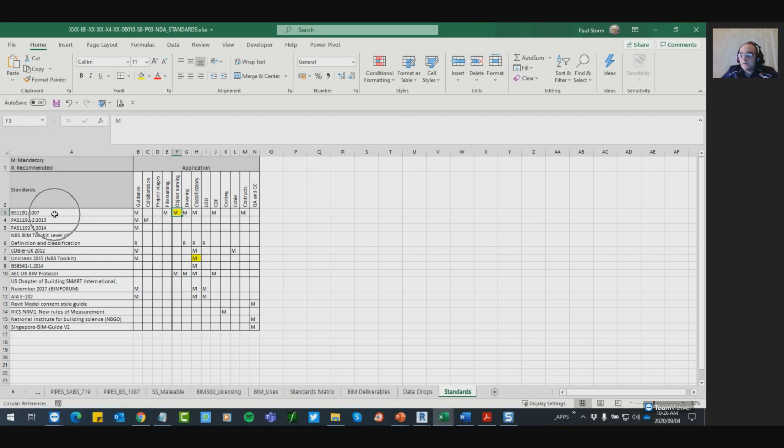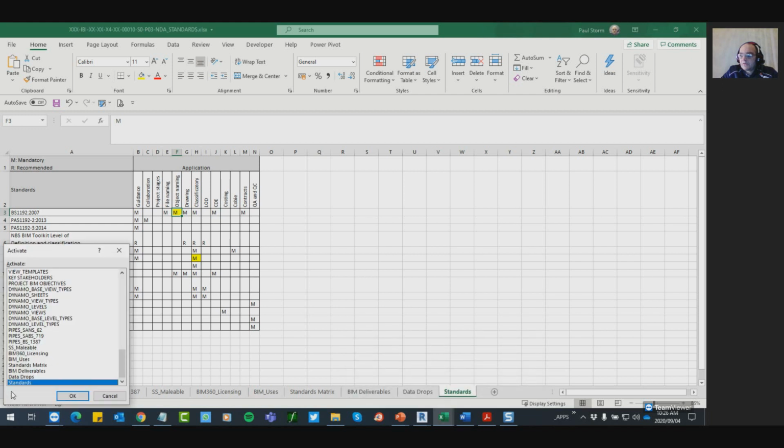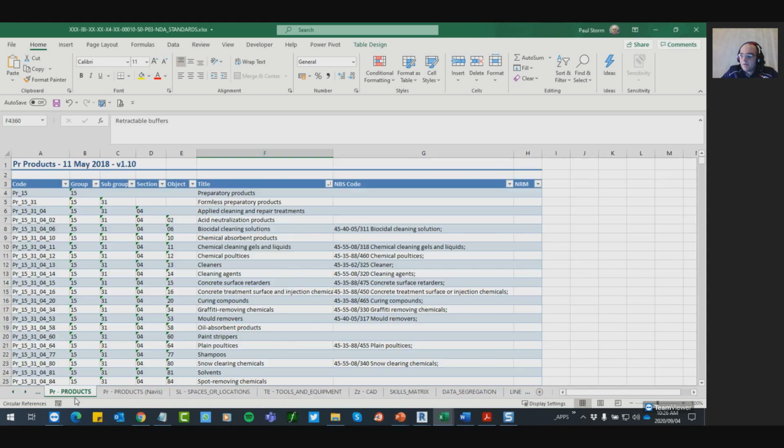If you delve into the British Protocol, you'll find that they require that you use it could be the SS, but mostly the Pr code to predicate the family with the code for the family, and then after that with the description before stating the manufacturer and the size and the level of development of the family. So it's important to be able to name a family.